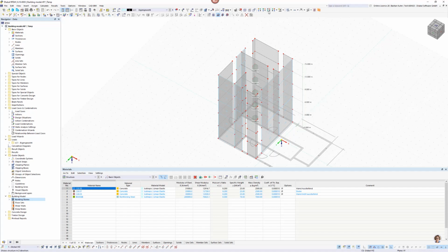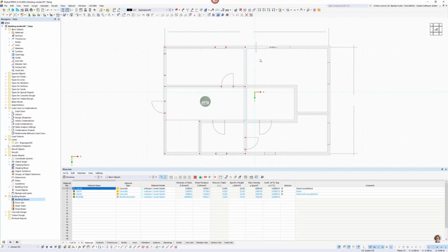So, and of course, I said it here in this case, we will need a few more posts and maybe we will put some kind of maybe a drywall or a masonry wall or something like this on this part in order to reduce the free span, because if I do not activate these walls in here, I will probably get problems with the deflection and the vibration of my structure.